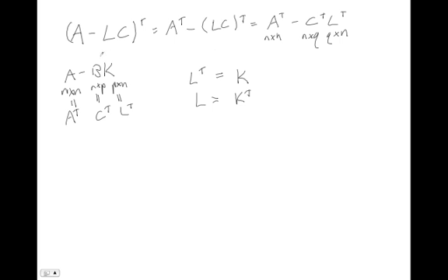So you can just take the method that you already have learned that Chen clearly explains for the multi-input multi-output how do you find K algorithm, and apply it for finding the observer gains L just as well. Now the truth is that this becomes very difficult in the multivariable case, and while these methods do exist, this is probably something that you're going to want to do numerically if possible, using MATLAB functions like the MATLAB function place. The function place will let you automatically find these values of K using A and B, and so you can use that algorithm to solve for this and also for this using this substitution here.